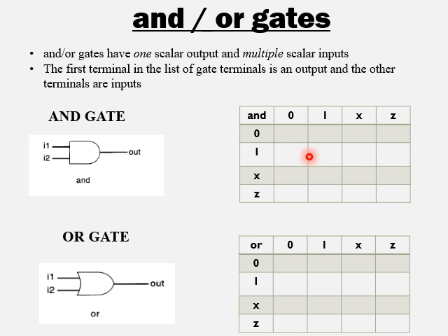If you recall, how do we do the module definition? We write the module keyword followed by the name of the module and inside the brackets we write the port list. And the next line we start with declaring the ports, that is depending on the direction whether it is input or output. Now once you declare any port as input or output, Verilog by default takes it as the default data type.